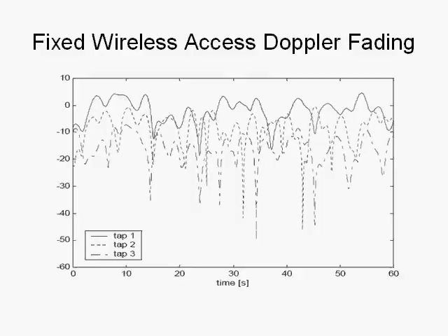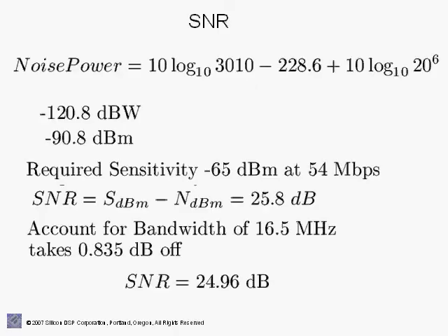both in terms of software and in general. And finally, we present many areas regarding systems engineering in terms of computing the signal to noise ratio based on the specifications of, for example, noise figure, bandwidth, bit rates, and so forth, so that you can actually design OFDM wireless communication links using 802.11a as a basis, but in particular in order to come up with the requirements to achieve the sensitivity you need in order to meet requirements in terms of range and throughput.